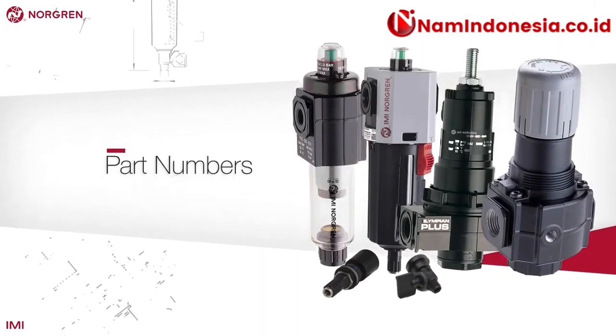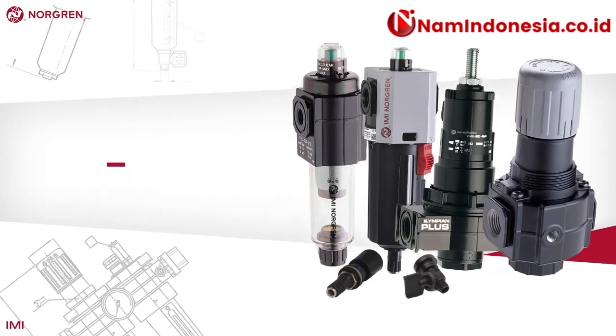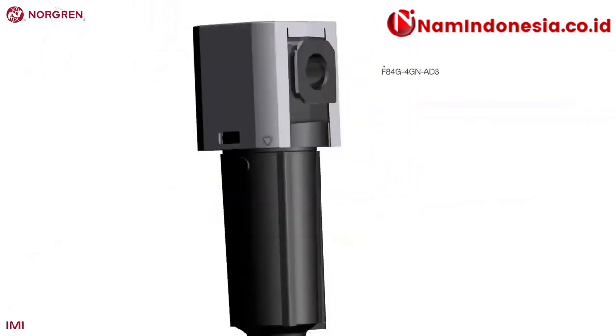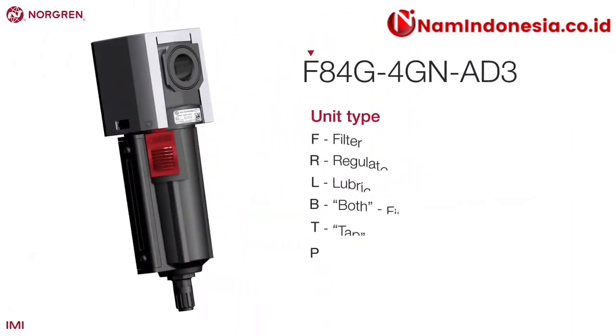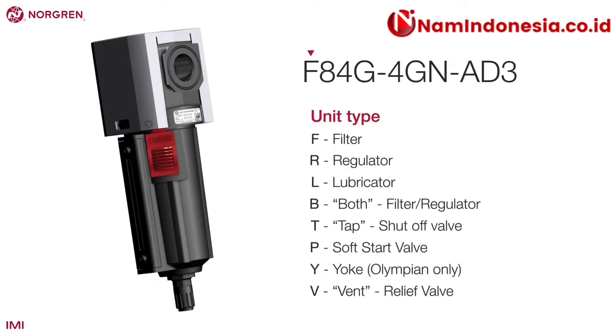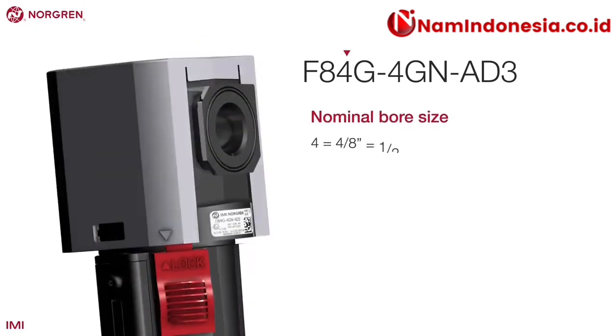Norgren has a formula for creating part numbers. This applies across the new range, but is especially relevant in air preparation products. Let's look at a part number. The first digit represents the type of unit, in this case, a filter. The second digit represents the product range, in this case, Exelon Plus. The third digit gives us the nominal bore size, which, as we mentioned, relates to flow. This is measured in 1/8 of an inch.